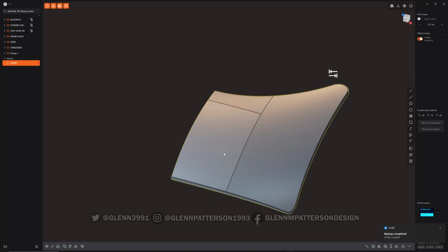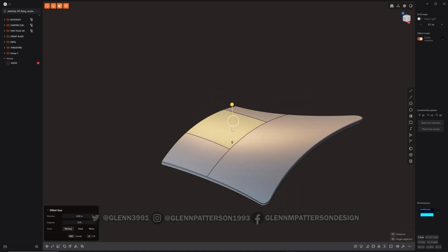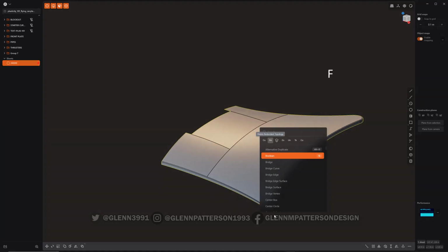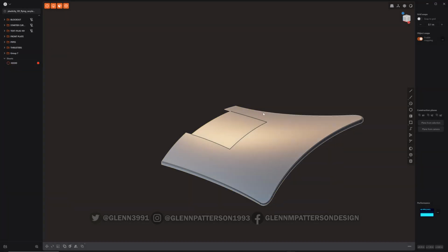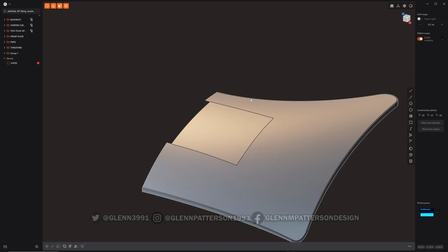We're gonna cut our little shape in here. Tab will always change that direction. Okay, cool. Go ahead and select that face that we don't want. Gone. And if you select on the body and search your commands, you can do delete redundant topology. It'll get rid of the extra lines for you. I've got it saved as a shortcut or a favorite.